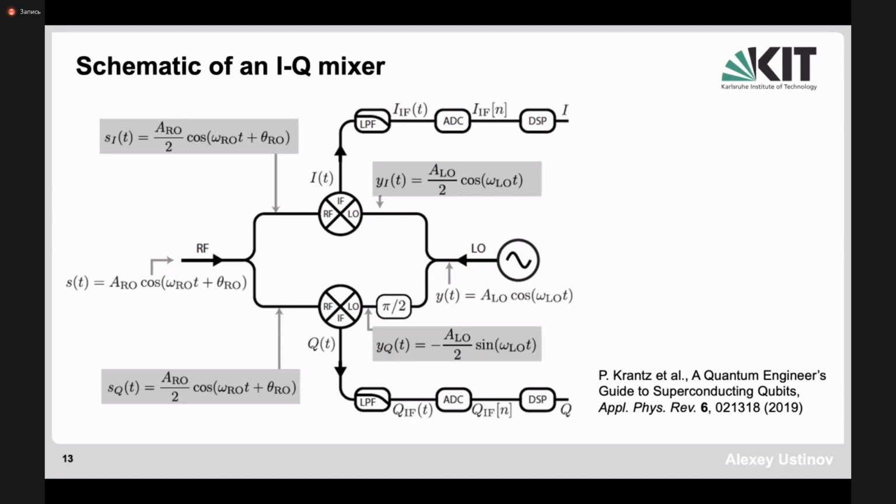Then one can encode different points in IQ space in different signals, and this is what is done in the cell phone communication when you have different users talking on different quadratures for the same carrier frequencies. So similarly, one can encode information in different quadratures, having both information in amplitude and phase. But the IQ mixer is simply a combination of two mixers, one of them shifted 90 degrees phase, and then either down converted for mixing or up converted for modulator.